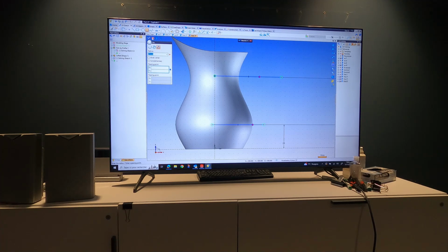What are we doing here? So I only have a measurement from the outside. This line is 30. So when I grab this, it looks for an angle, not a... Yeah, normal. So you can select the center. So you know the radius. The radius is 25, so it's 30 less 25. And you take the center. And that's going to be 5 off of here, I guess? Okay.